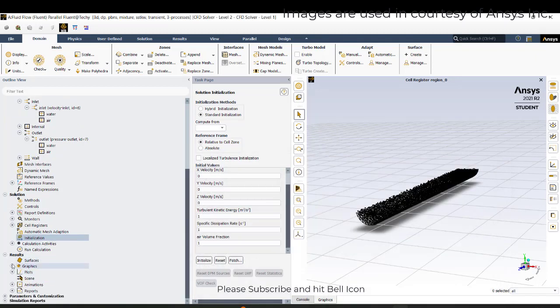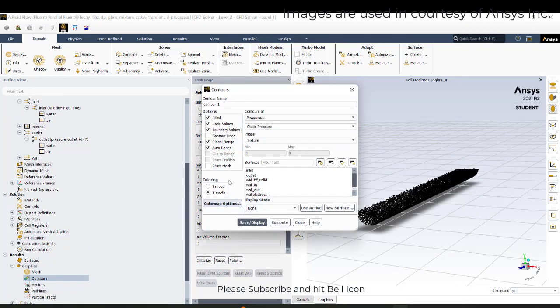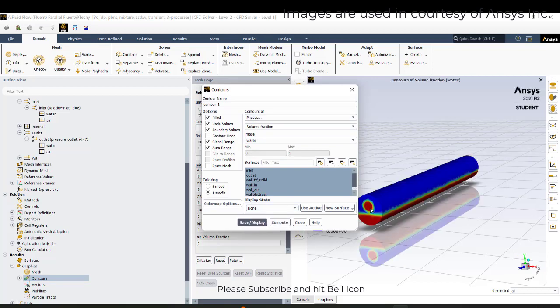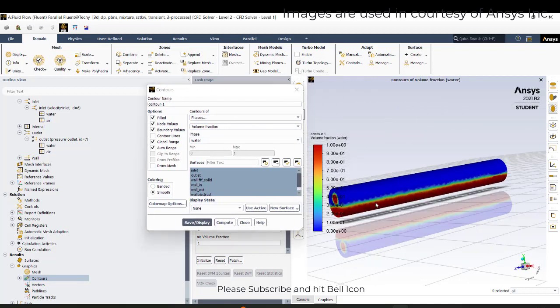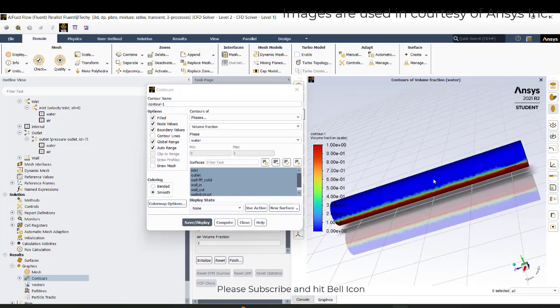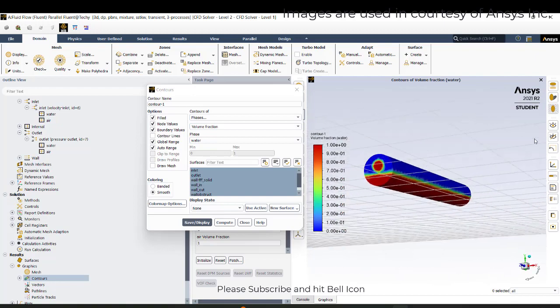Now you can go to the graphics and check the contours to see how exactly it looks. You can just select this, go to the faces and check for water. You can see here the bottom is completely filled with water, and here at the inlet there is no water, only air, so it was showing in red color. So I think it is okay.